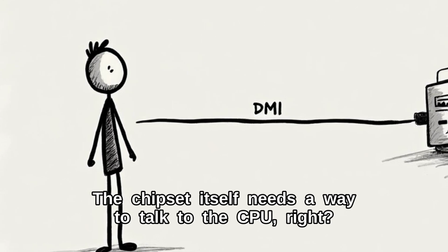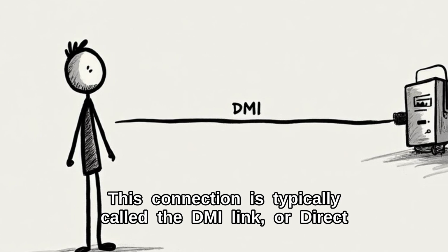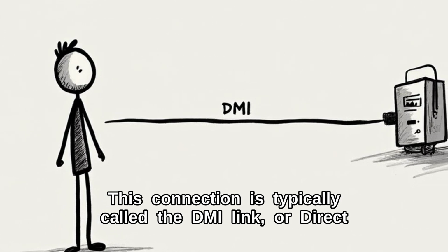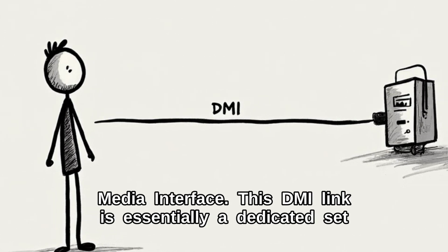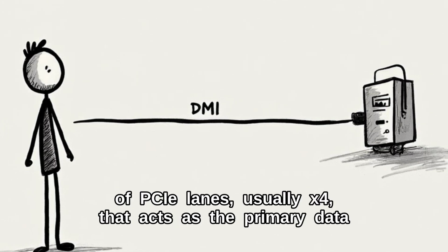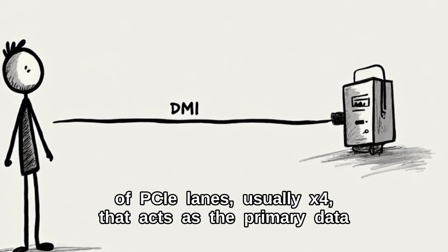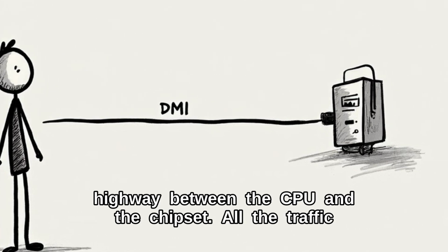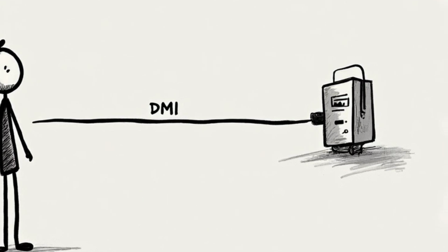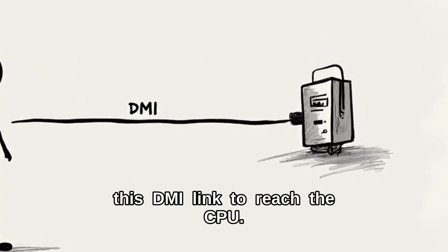The chipset itself needs a way to talk to the CPU, right? This connection is typically called the DMI link, or Direct Media Interface. This DMI link is essentially a dedicated set of PCIe lanes, usually X4, that acts as the primary data highway between the CPU and the chipset. All the traffic from the chipset's connected devices has to flow through this DMI link to reach the CPU.